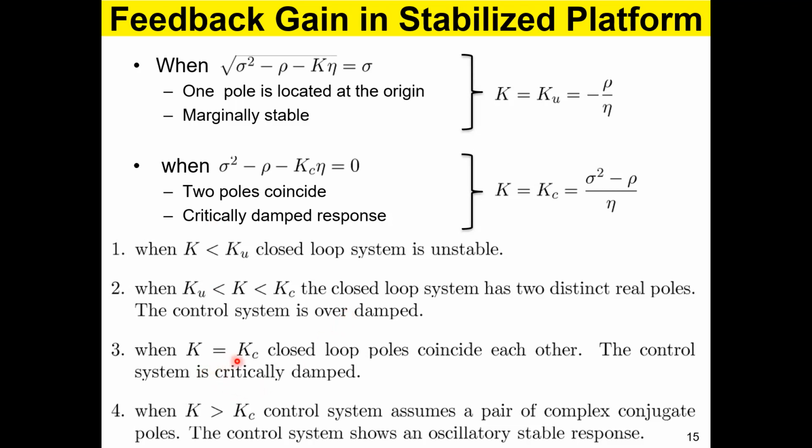Now, when K equals Kc, the critically damped system is somewhat faster. There's no delays, kind of efficient, like our private sector maybe. And then if you increase K further from Kc, the system becomes oscillatory, but it goes beyond what you really want and then comes back, a rebound, and then goes up again. So it goes up and down, oscillations, and it settles at the right place.